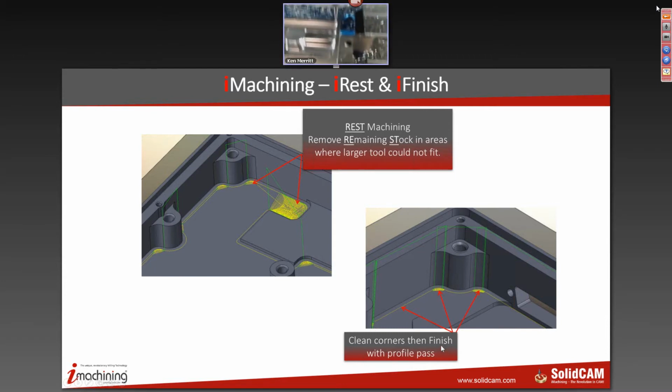iFinish is a very, very interesting module because most people don't think about this. You guys have all seen the diagonal lines in the corners and heard the chirp and the chatter when the model radius is very, very near the tool radius, okay? What iFinish does is actually analyze the topology of the model for those over-engagements, and it goes in and picks those corners out first using the D-slot trochoidal down to the minimum cutting angle. And then it allows the contiguous toolpath to come through here on a finish cut and not over-engage, but also not under-engage. So we're not going to burnish the tool. We're going to wind up with a really, really nice surface finish through those corners. Okay, very, very powerful system for that.